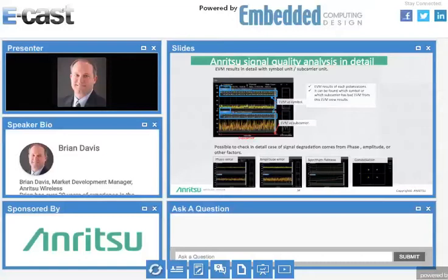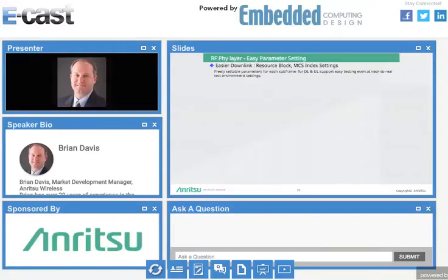We can also take a lot of measurements and combine them together too. So we can look at signal quality analysis in different views. So here we can put EVM measurements across symbols, across subcarriers, and do a comparison to see if you're seeing strange issues going on in different kinds of measurements there. Same thing with all the other measurements that I talked about too, so phase, amplitude, spectrum, and then constellation as well. And a lot of these you can look at simultaneously as well. You can break them out into 4 different plots and look at them simultaneously.